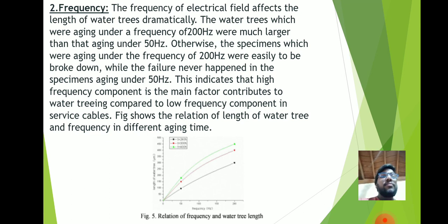The figure shows the relation of length of water tree and frequency at different aging times. When the high frequency component is present, the length of the water trees increases. The high frequency component is the main factor that contributes to water treeing compared to the low frequency component. This is figure 5, the relation of frequency and water tree length.